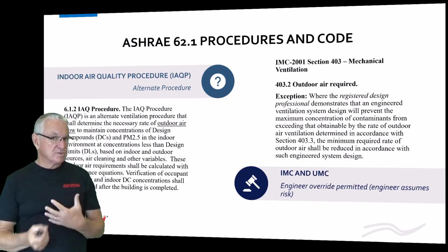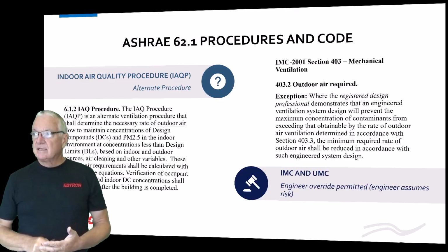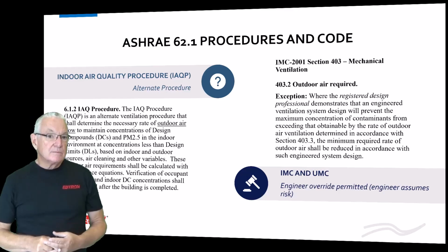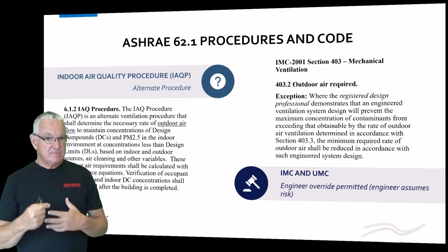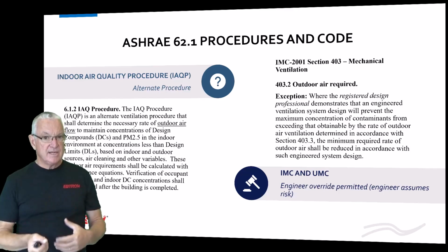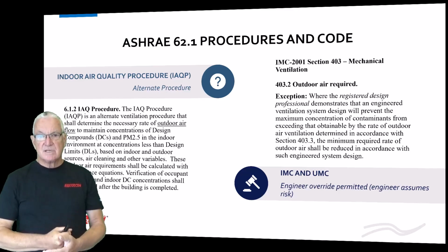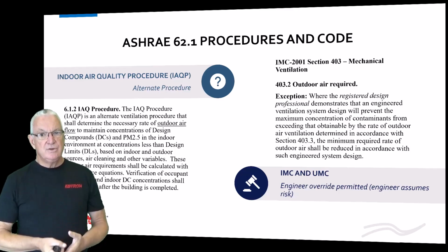And there's a whole procedure for testing the building. And I do think that could be a problem for a lot of these buildings where you've made a claim to reduce the outdoor air based on air cleaning, okay? Because when you go over to the IMC and you look at the IMC, there is a provision for you to do this, okay?